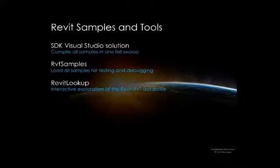Three items you should be aware of within the SDK are the Visual Studio solution, which enables you to compile all of the samples in one single go, and the RVT Samples external application add-in, which enables you to load all of the other samples for testing and debugging, meaning that you just install this one single external add-in, and then all of the other add-ins become accessible immediately.